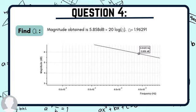To find the alpha, we first need to find the previous frequency on the magnitude Bode plot, which is 5.858 decibels. Then to find the alpha, 5.858 decibels is equal to 20 log alpha, which makes alpha equal to 1.962.